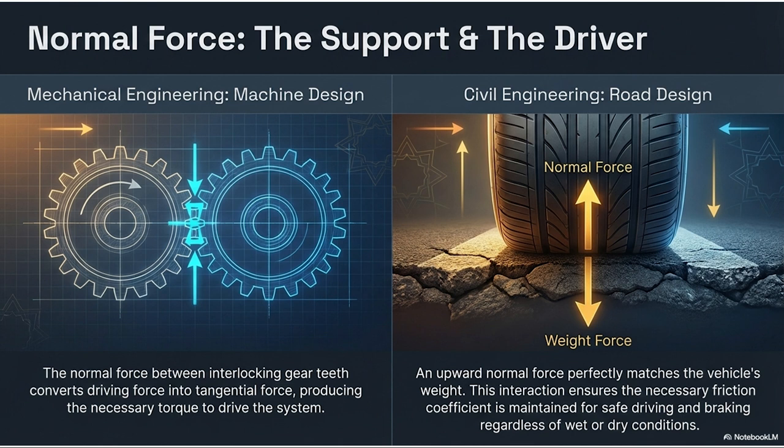You'd just skid infinitely. Yeah, the grip of your tire is directly proportional to how hard the normal force is squishing the rubber into the pavement. This is why a heavier car can sometimes take longer to stop. The weight increases the normal force, but the momentum it carries often outpaces the friction those tires can realistically provide.